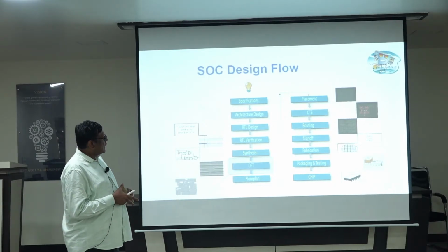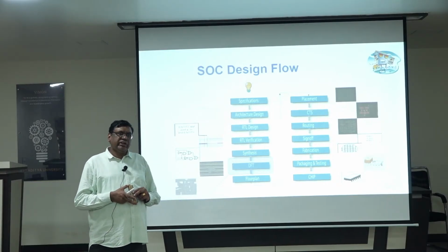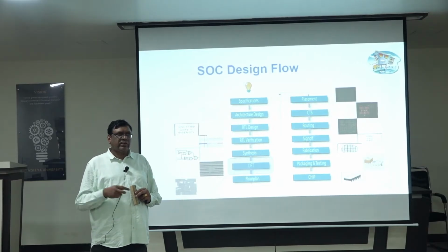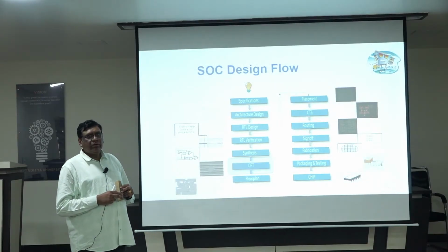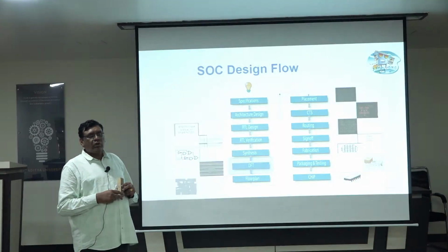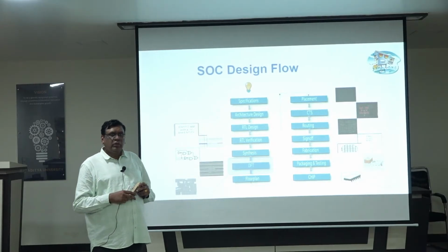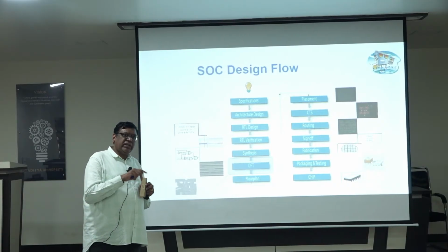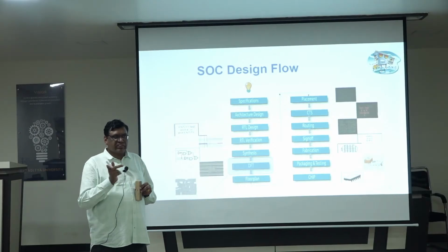Then it comes to RTL designing, where the specifications will be converted into hardware description languages. You can use Verilog or VHDL, whichever language, but it has to be converted into RTL form. RTL is nothing but register transfer logic. Once it is converted, the RTL has to be verified. Many techniques are there to verify the functionality. That verification and what we call testing are completely different. We will come to that discussion.